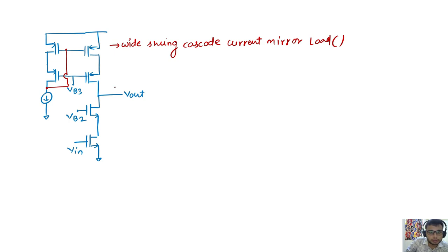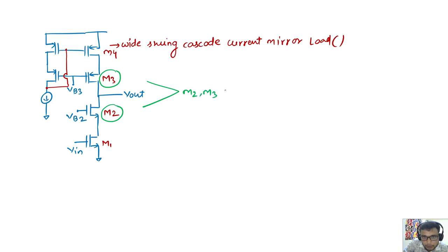Okay, so this is also a cascode device. My motive here is that this is my M1, M2, that I call M3, I call M4. What we see here is that two devices, M2 and M3, these are the cascode devices, so cascode devices M2 and M3 will contribute no noise. So the conclusion is that we can directly look at the cascode device.